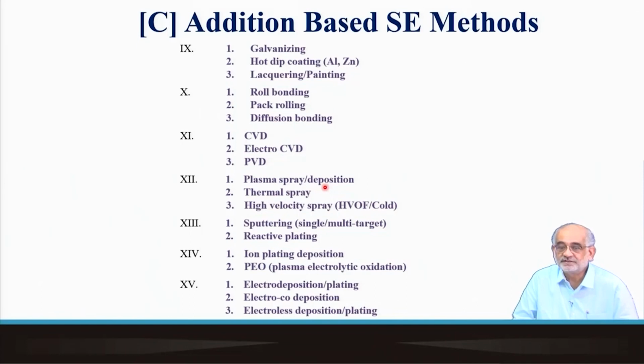The extreme could be the cold spray method, where you just take powders of certain geometry and size and throw them at supersonic velocity on the surface of a substrate, and the substrate develops a thin coating, and eventually you can make a fairly thick coating by only spraying such powders at a great velocity so that the powders not only impact on the surface, but in the process of impact they also deform and form diffusional bonding, grain bridges.